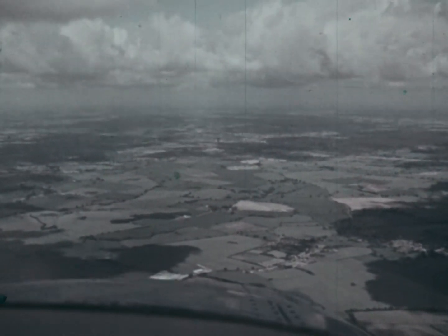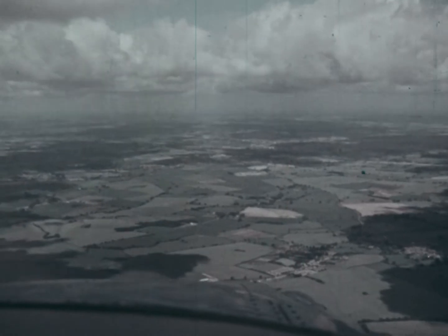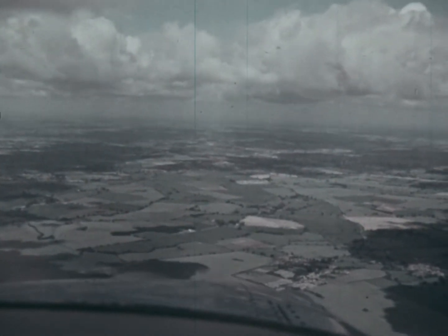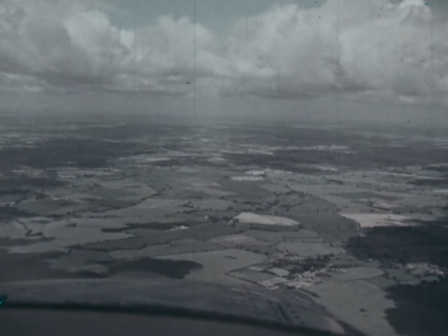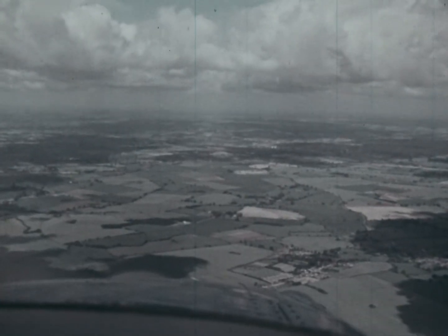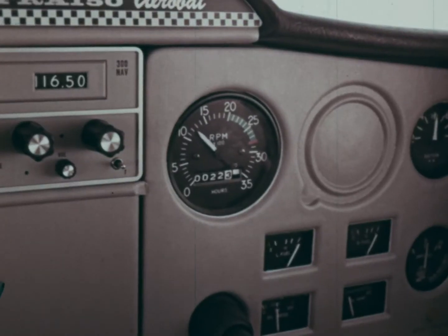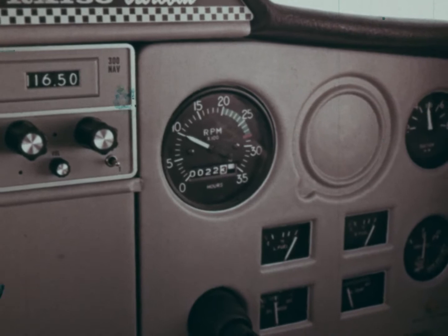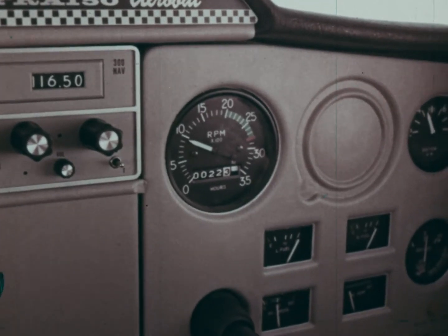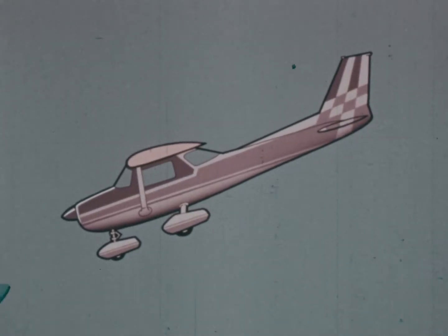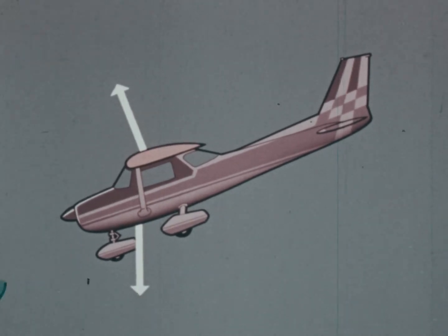Beyond a certain angle, the descending flight path becomes a glide. There is now enough weight acting forward along the flight path to keep the forces in balance, and thrust as such is no longer needed. Even in this situation, the forces remain in balance, and a steady speed is maintained on the glide path.